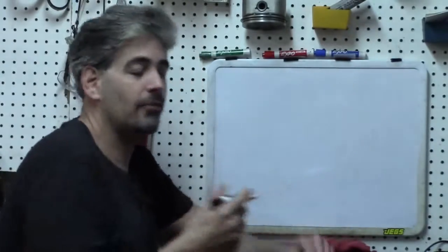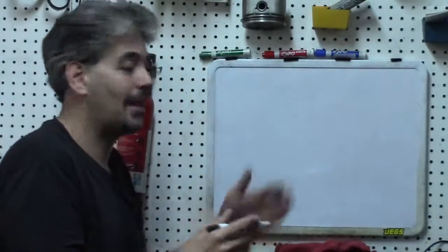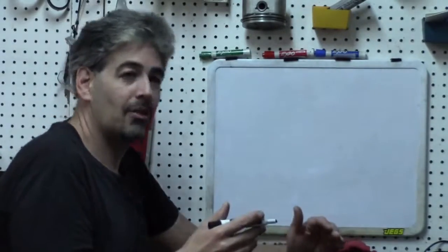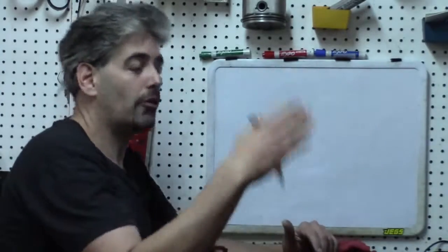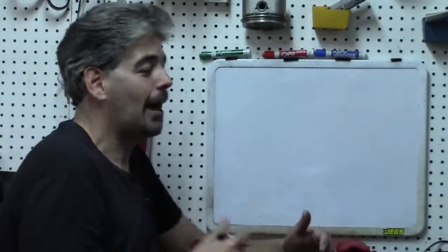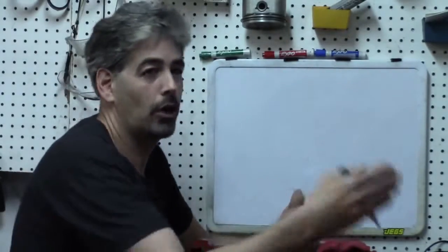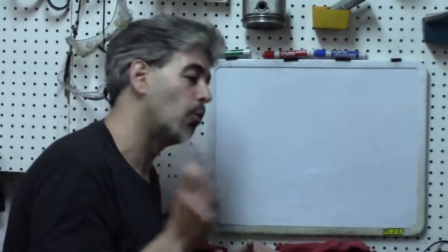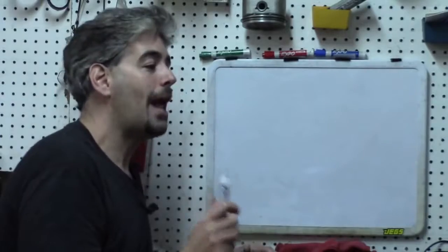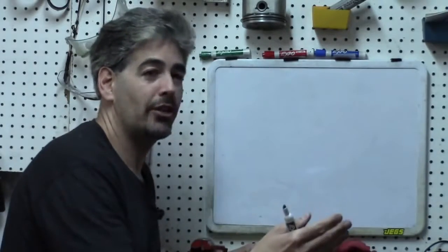A case in point, very commonly people who diagnose a fuel pressure problem, they look in the flow guide and it tells them at some point remove the vacuum hose from the regulator, and then you look for a fuel pressure change. Is it supposed to increase or is it supposed to decrease? Well, you have to look up and remember. You won't have to do that, I promise. For the rest of your life, you will always know what happens when you remove the vacuum hose from a fuel pressure regulator and what you should expect.